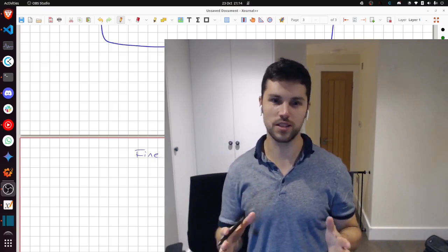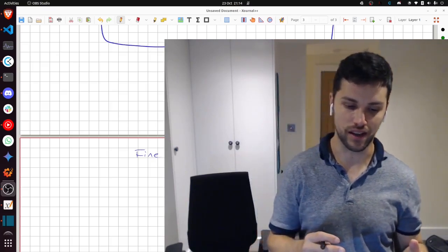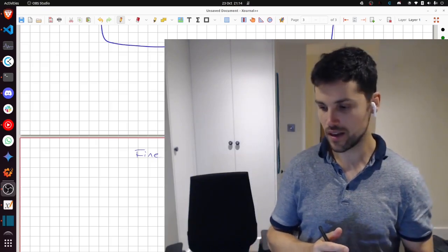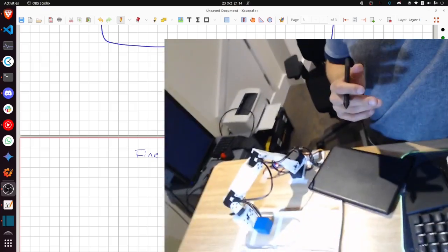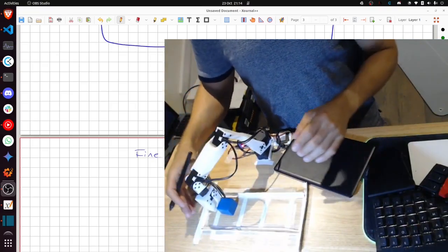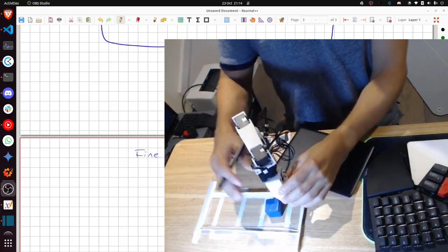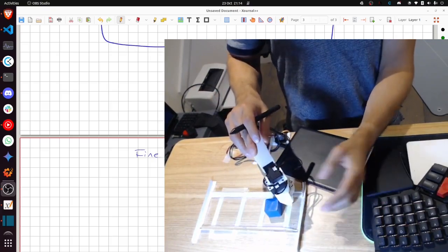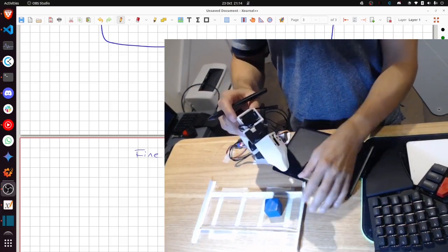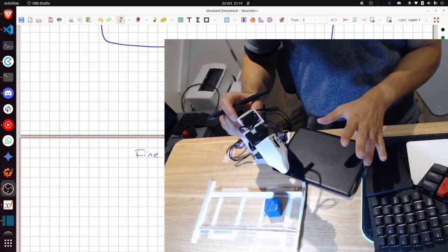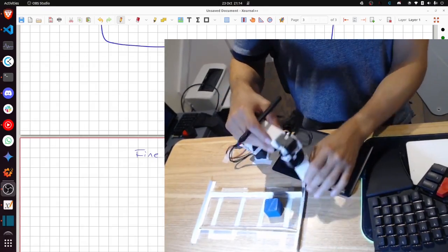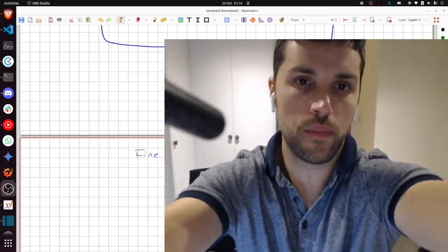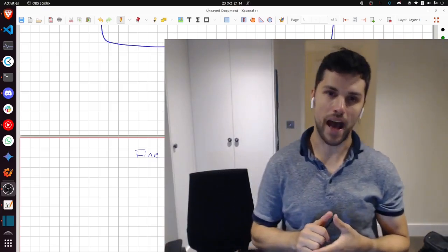But there's a whole other aspect here, which is the world model and understanding the value function throughout the state action space. So what was happening was, when I finished training the offline part, I'd set the arm here and start the model running, and the arm would just whack the table, or it would go up. And these two were out of bounds conditions for me, which would give a large negative reward. So the arm would always just do something crazy and wouldn't move towards the cube. And the reason is because I'd not given it any bad data.